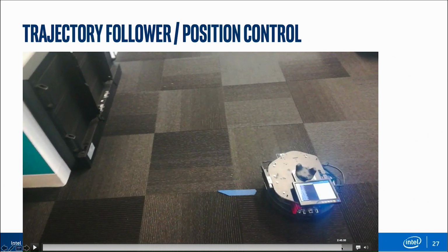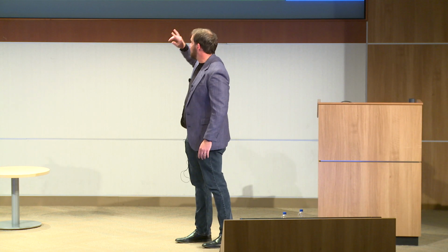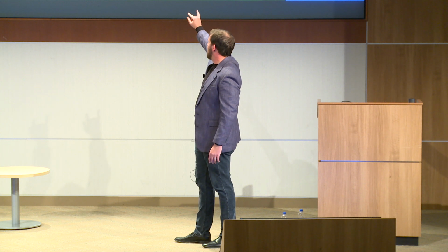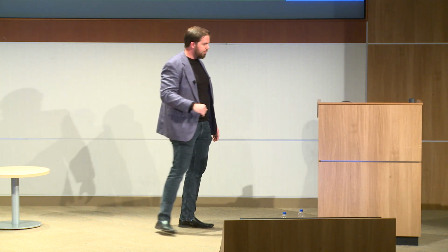That we can assess the accuracy by the loop closure error. It is coming back to the same spot after traveling a distance of 48 meters, and is coming back to the same spot with below 15 centimeter, which is less than 0.5% of the path length.